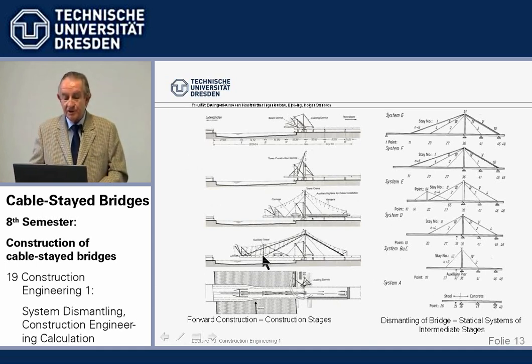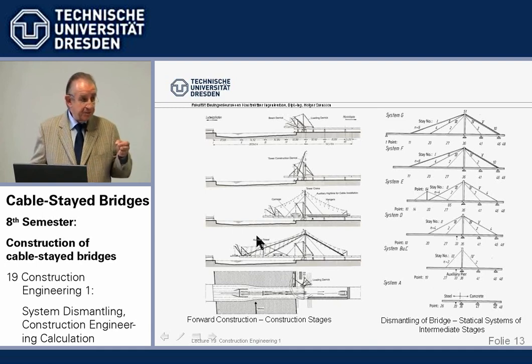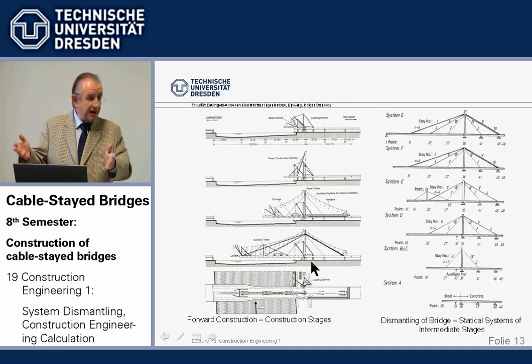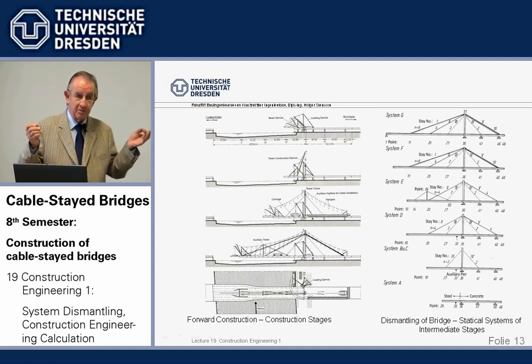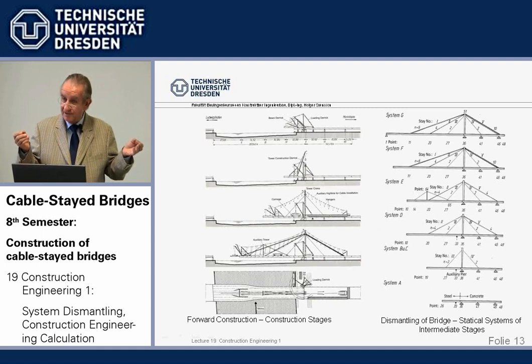We could have left out this auxiliary stay here, but that would have meant considerably strengthening the steel plates here. So the contractor said, that's very expensive. I'd rather use a cheap auxiliary strut and some additional work, and by that, the steel plate thickness for the final stage is sufficient also for this erection stage. One has to balance the costs. You remember, for university it's not usual, I know, to talk about costs. But in real life, it's the name of the game.